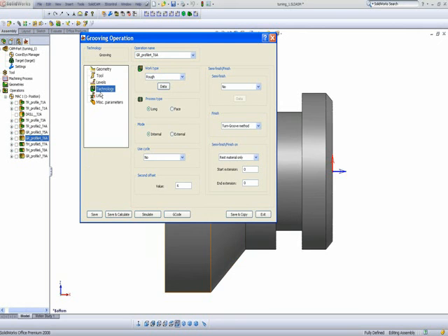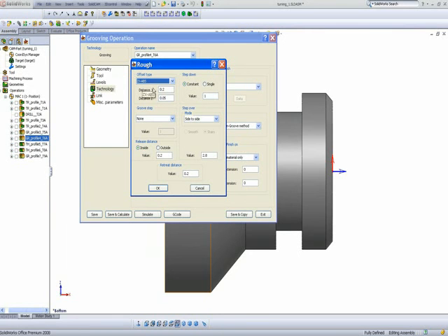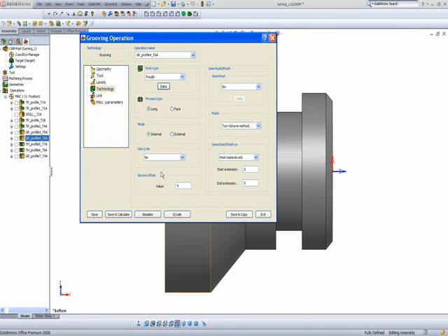My technology area, since I am working a grooving operation, I'm working again long, but I'm working this time internal. Again, I have in my data area the amount of material I want to have left over if I want to work from side to side. And again, my finish, I'll be using the turn groove method.